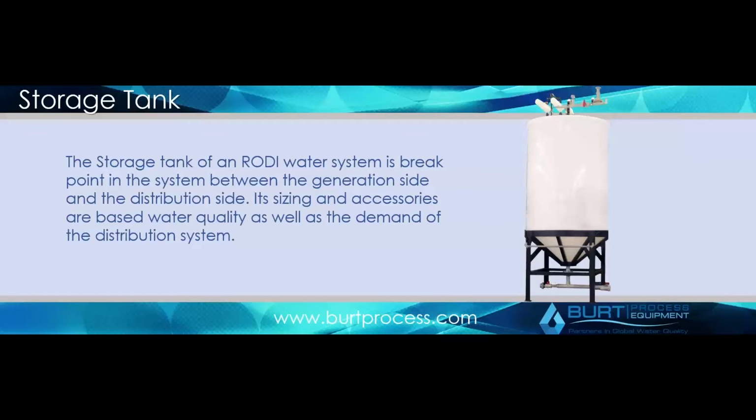So as you draw off of the tank, you go through your resins, your filters, your UVs, you're ultimately going to pass back through your loop, and then you're going to come back through your return header here and into your actual storage tank. And this is sized based on what the drawdown rate is of your loop, but also on the makeup rate and your water quality. The higher the water quality, the smaller the tank, because it's very hard to keep a tank like this very clean for an extended period of time, even while you are doing that polishing.